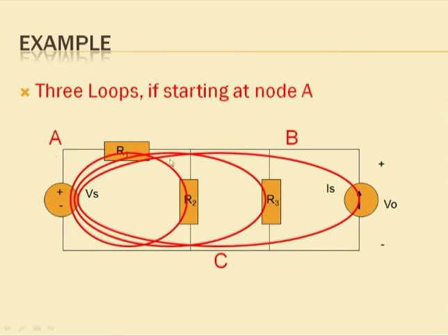If I am considering the voltage drop positive, then I must consider voltage rise negative. One can think in the reverse direction also, but you have to decide which convention you would like to follow, and it should remain the same for the analysis of a given circuit.